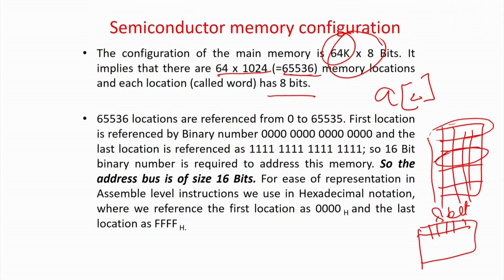In fact, very similarly we can write it as an array of size 65536 by 8, but the only thing is that these 8 individual bits cannot be accessed, you can address the whole 8 bits at a time. So, this will be called a byte accessible memory, because one word or one byte can be accessed here. And how do you read out the locations?